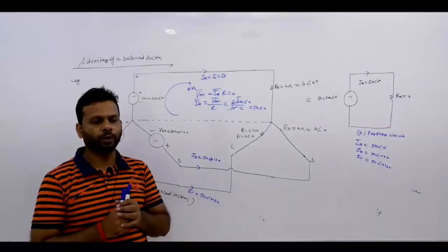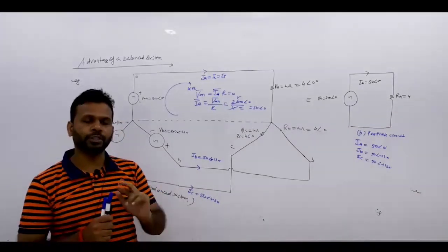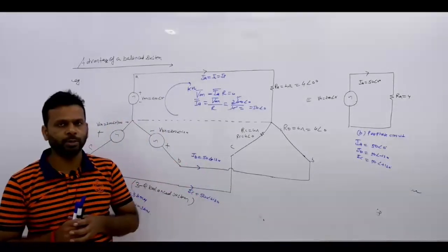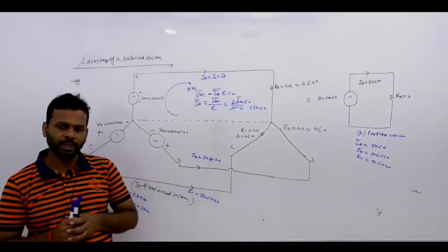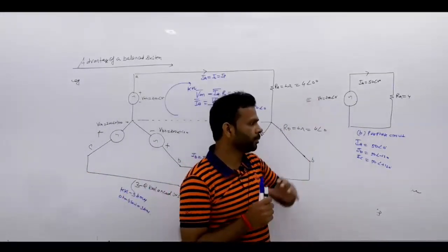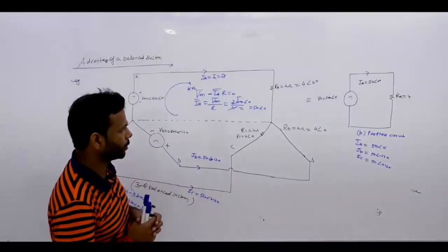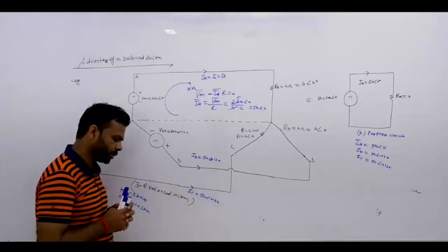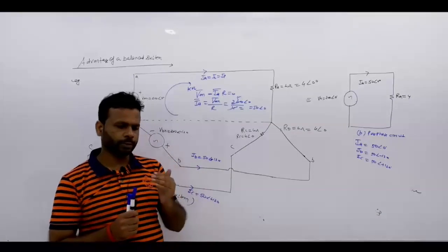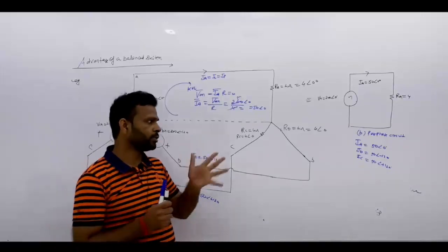And in your power system, all the single line diagrams or one line diagrams are per phase diagrams, because in the transmission system, generating system or distribution system, we are assuming that all the phases are balanced, and for a three-phase balanced system, we are taking the assumption that it is per phase. So it is much better to have per phase circuit analysis. Your three-phase synchronous machine example is drawn with respect to per phase, and in the power system the single line diagram, the one line diagram, are per phase diagrams.